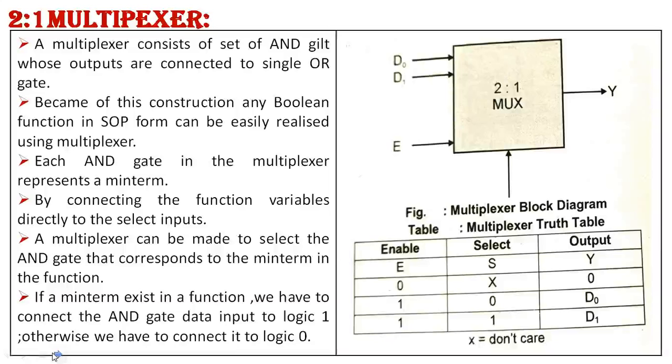So that is the diagram of the 2 to 1 mux with its corresponding output, using E enable to activate that IC, and the downward arrow shows the select lines. When the enable is active on the 2 to 1 mux and we select 0, we get the output D0, and when the select line is 1, we get D1.